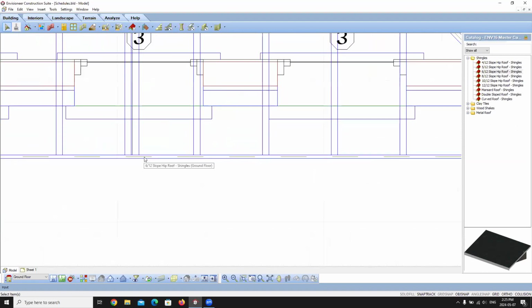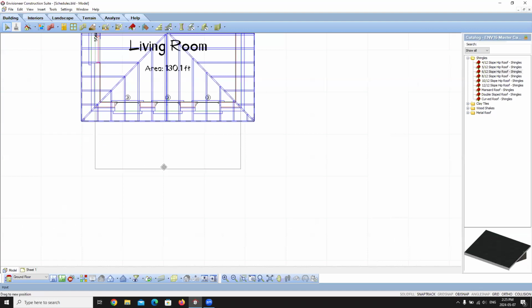So again, if I go in and I select the edge of that roof and I stretch it out, the roof shape will change, but the members stay in their exact spot because we've basically broken the association between the members and the roof. So only do this when you know you're finished with the editing of the roof. And I'm going to Control Z back.